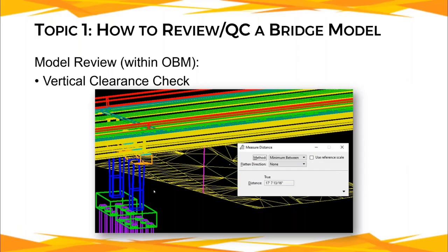So this is if we're putting a bridge over an existing roadway and we're not doing anything to that roadway. If you had a proposed roadway model, you would then just have to make sure that you have a terrain file extracted from the roadway model. I've been told that that is a setting that can be enabled when roadway does their models, to have a terrain file created, basically a surface created from the surface of the roadway.